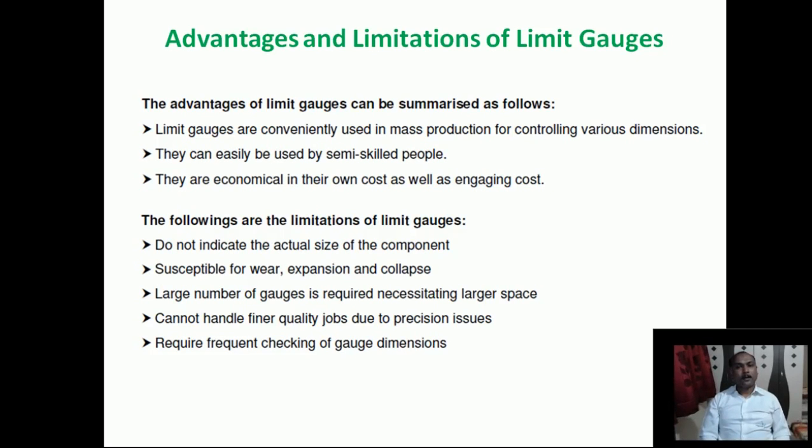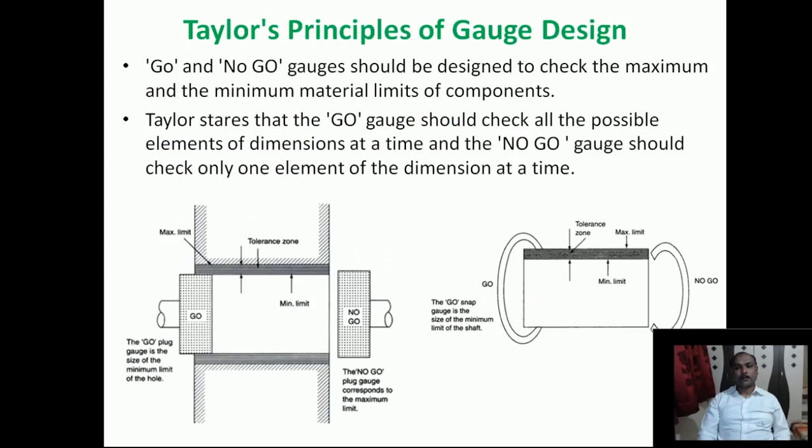It cannot handle the finer quality jobs because the dimensional accuracy is limited. And frequent checking is required because the wear will take place, and we have to check whether the gauge itself has the required accuracy or not.